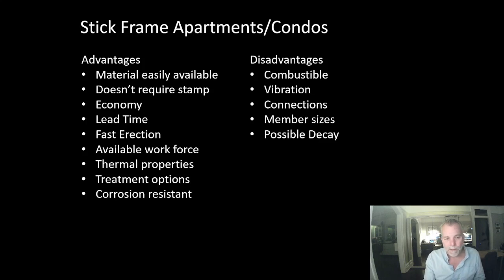Very economical. Without a doubt, it's the most economical way to build. Very fast lead time. So there's no prefabricated elements. There's no shop drawings or limited shop drawings that need to be produced and reviewed. It's very fast for erection, so it's a short time on site. Not only is it fast, but winter construction is easy with stick frame. There's a large available workforce, so it's a relatively low barrier of entry for the workforce, and therefore there's a large available workforce.